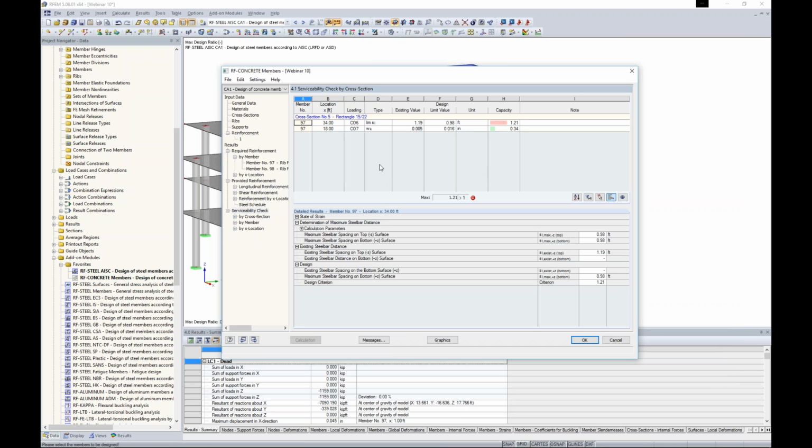This is more so in table format. Looks like we're a little bit overstressed, or not overstressed, but our limiting crack or spacing for our torsional reinforcement is exceeding the capacity here. Well, this is a good example here of a live webinar. It was passing before, but it looks like now we aren't passing, so maybe we'd want to go back and address some of the spacings for our longitudinal and shear reinforcement to meet those code standards.